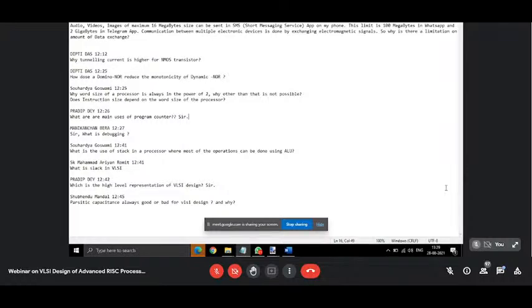So when we are generating the micro operations and write the state table, should I keep the state table or the micro operations instructions within a LUT, or is there any other way? No, sir, for RISC, LUTs are not used basically because it will be slower. LUT means what? The memory access. And memory access is always slower, isn't it? Yes, sir. So that's why any hardware RISC architecture is based on hardware control logic. And to reduce the complexity, the number of instructions is restricted to a minimum.